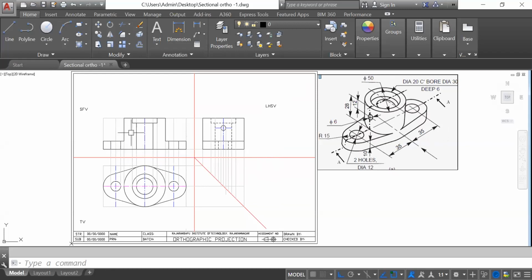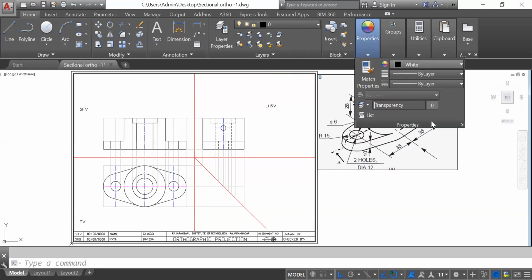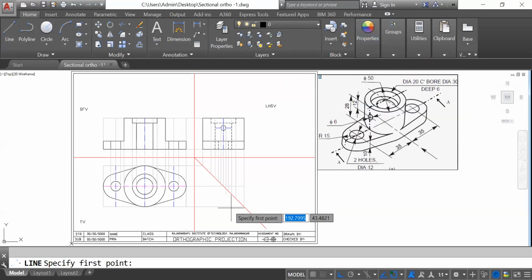Okay, so you will get a structure like this. Also there is one keyhole of a diameter of 6 mm. After completion up to this, you can go for the side view. And how can we prepare the side view? You just have to take the projections. So I have drawn the side view here. You just take the projections from here.